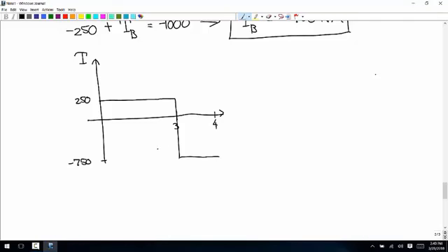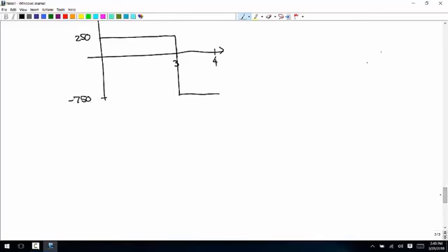And so you'd have to decide whether you want to calculate the angle of twist. It won't matter either way. Okay, so the angle of twist is the internal torque times the length divided by G I sub P. And we're just going to do it over those first 3 meters.